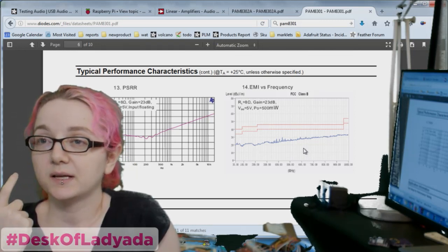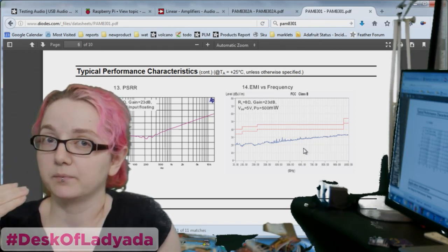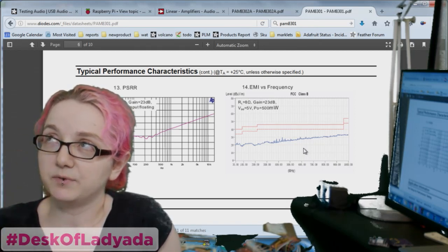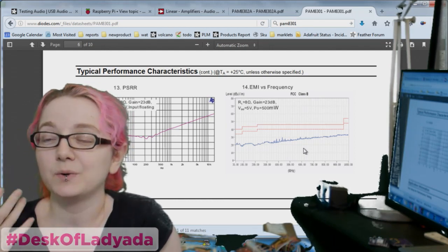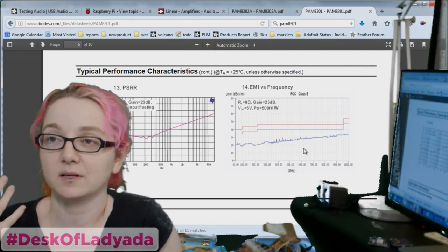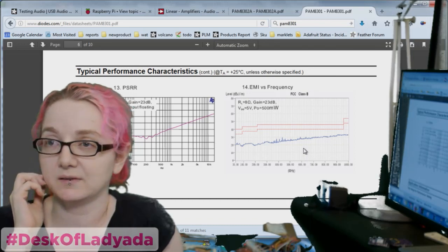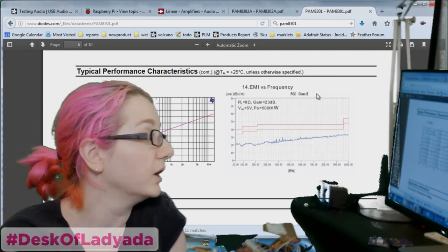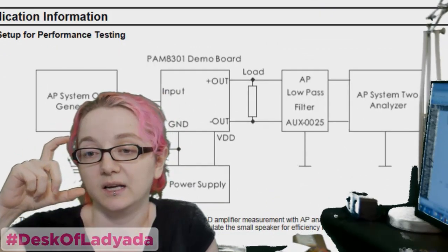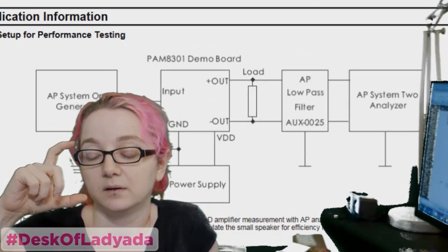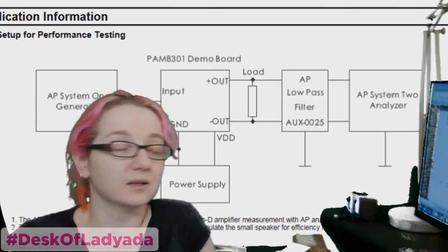Which also makes me think I could just do a single transistor, like an emitter follower, which would basically act as just a current gain rather than a voltage gain. The output of the DAC is going to be 3 volts peak to peak, and you can't put 3 volts peak to peak into these little speakers anyway, so you're not going to be able to push that much current. So I can reduce that voltage by dividing it in code in the DAC.